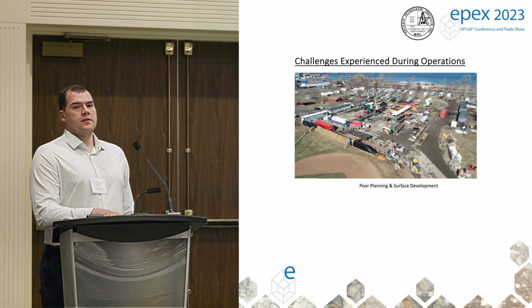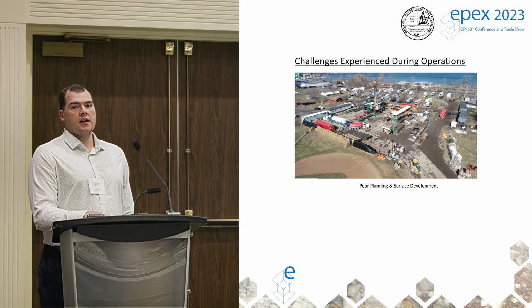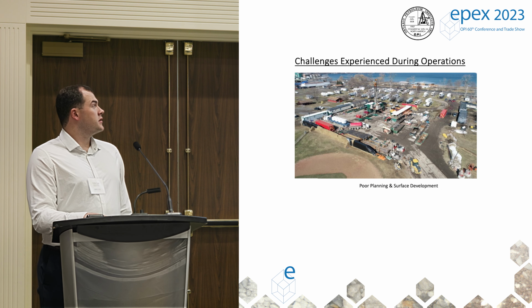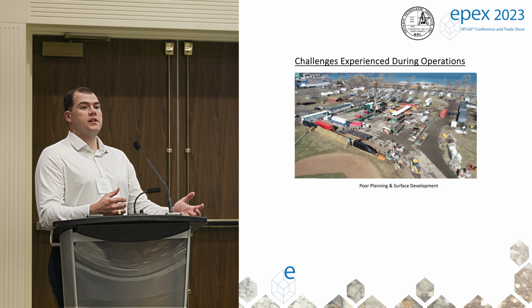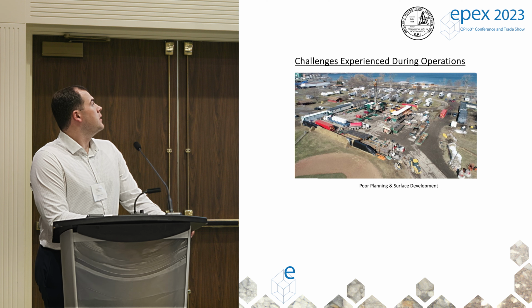That ultimately drives the cost of your well up, especially on your surface casing with a hole that size. And with something that shallow and unconsolidated, typically till you get to hard rock, you're also going to have hole stability issues with it staying open long-term. It's going to want to fall in on you because you don't have the hydrostatic head keeping that borehole open.